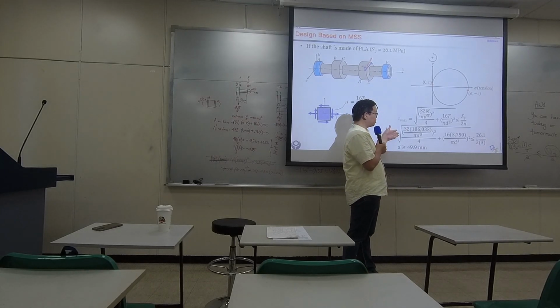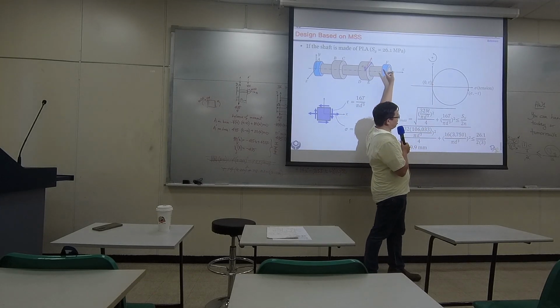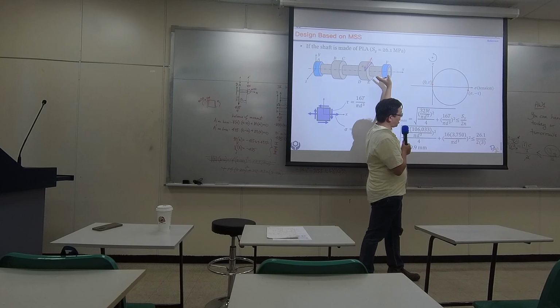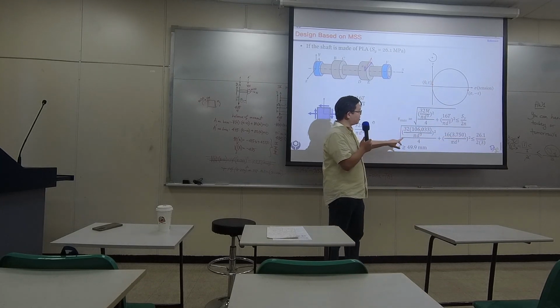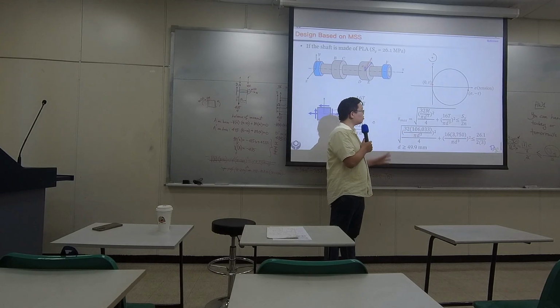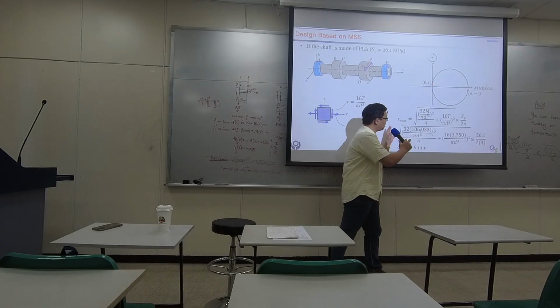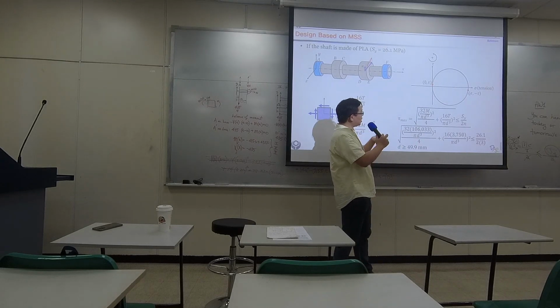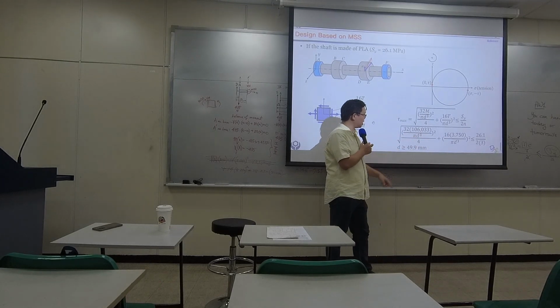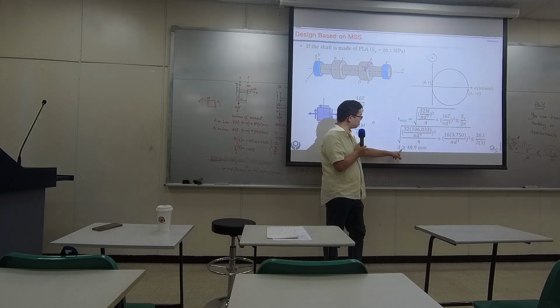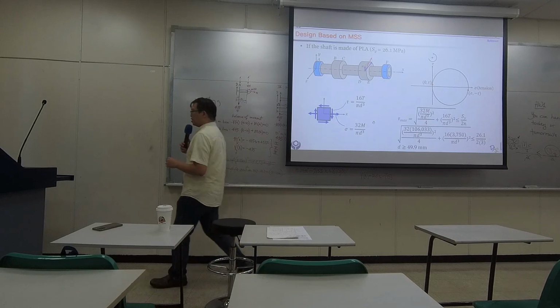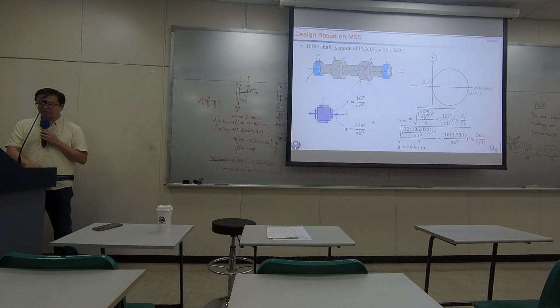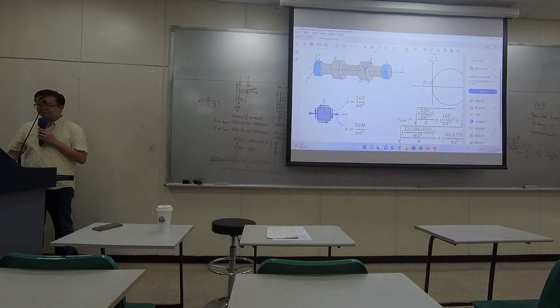Also, we chose to stay with the 3D printing material, PLA. So my yield strength is 22.1. The only thing left is D. So what you can do is to clean up, formulate this equation, and then try to solve for D. At the end, you realize D must be greater than 49.9. What was the value that we used for the problem?